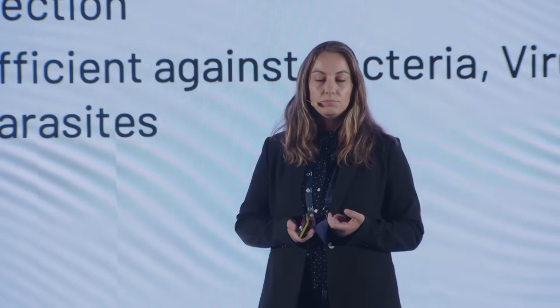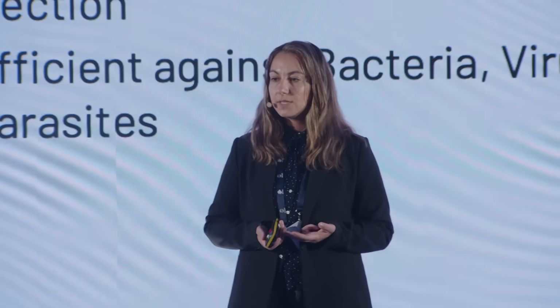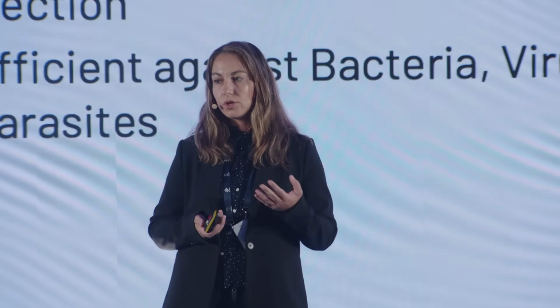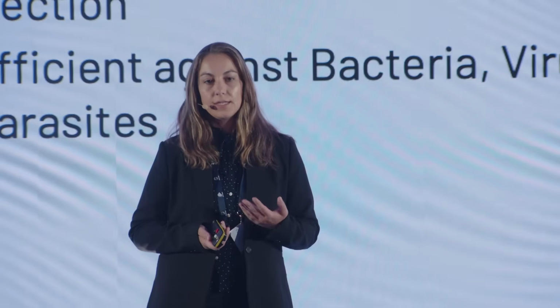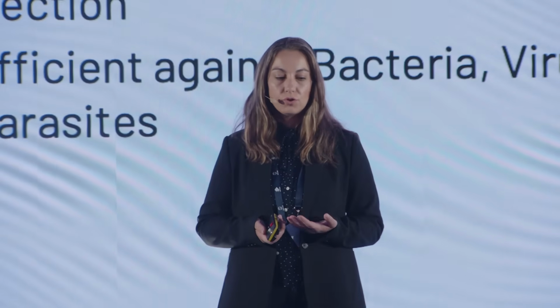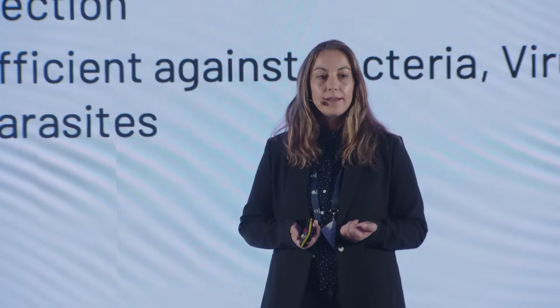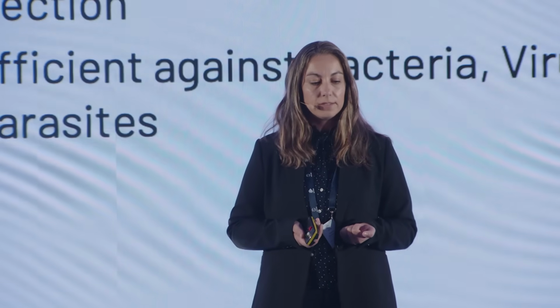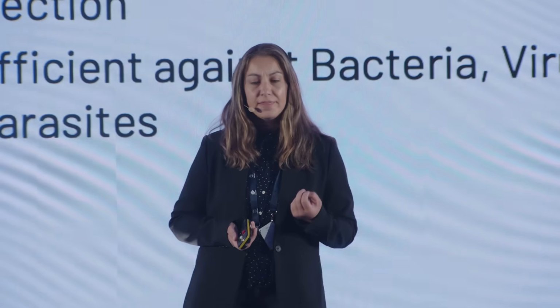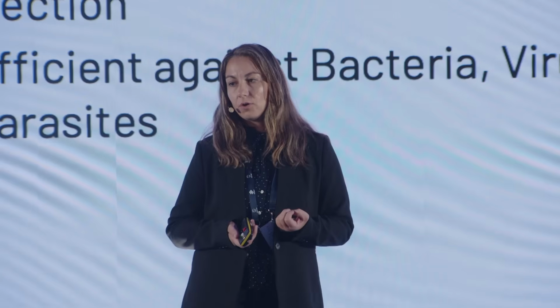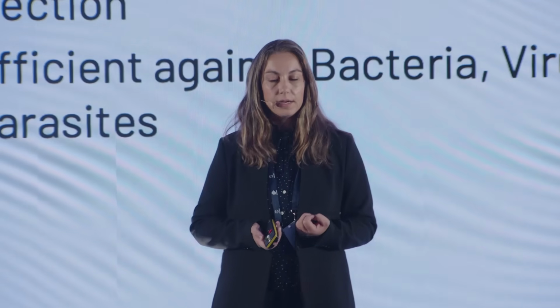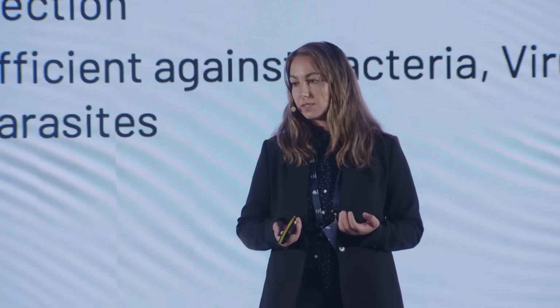A very good characteristic of ozone is the hydroxyl radicals. When ozone decomposes, hydroxyl radicals are formed, which are the strongest oxidant that you can find. They are highly reactive, non-selective, and they can react with compounds that the ozone alone can't deal with, like geosmin and some other resistant compounds.